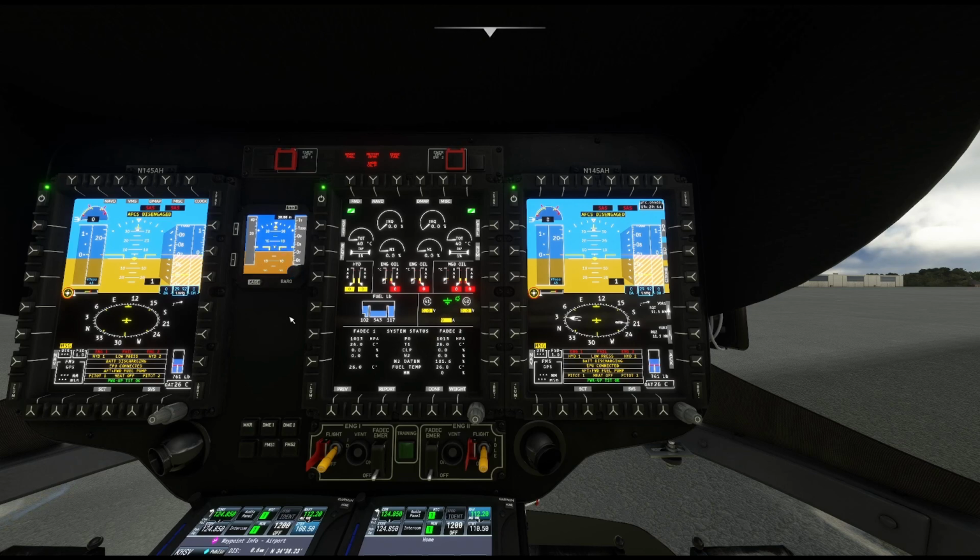So when you guys are setting your barometric pressure, really what you should be doing is you should go to this side, 2992, let's go to 3002, 3002, 3002. And then we would say, all right, set left, right, and center. All right, this controls the brightness of it. This recages it and realigns it, and then this brings you back to standard.